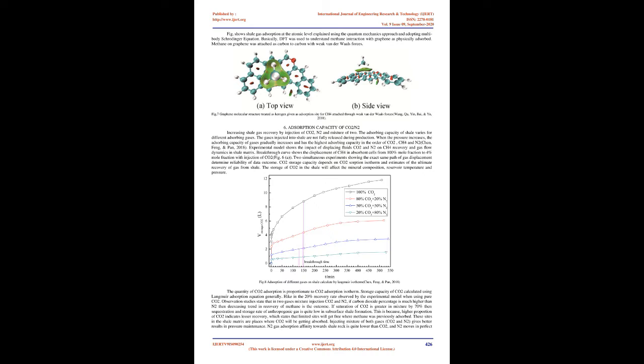The adsorption column in the experimental setup is treated with methane at different pressures ranging from 5 to 15 MPa at 318 K and left for 4 to 10 hours for adsorption until pressure reaches the equilibrium stage. After reaching equilibrium pressure, displacing fluids such as carbon dioxide and nitrogen gas are injected into the adsorption column in different proportions such as 100% CO2, 100% N2, 50 to 50% ratio of CO2/N2 mixture, 20 to 80% ratio of CO2/N2, and 80 to 20% ratio of CO2/N2 mixture.